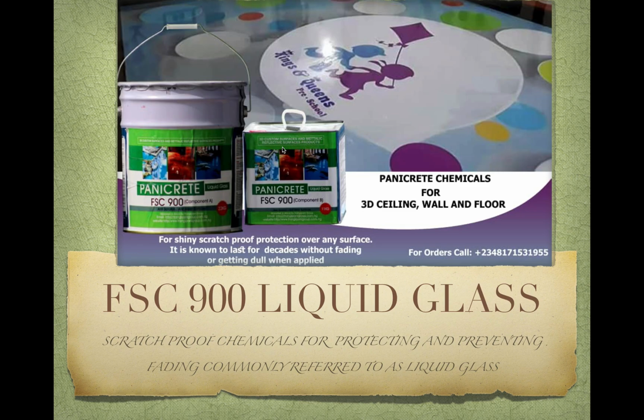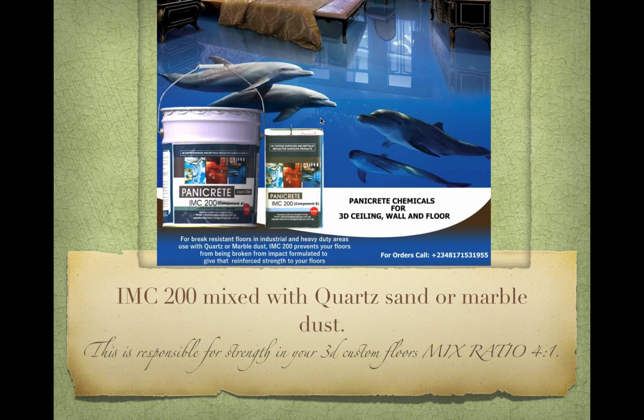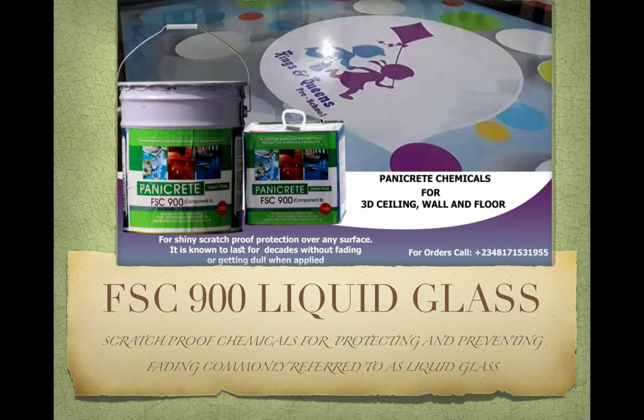Then you have the FSC 900. The FSC 900, also known as liquid glass, you use that to protect the vinyl. After you install the IMC 200, 12 hours later after it has dried, you bring your 3D image and place it over the floor. Immediately after placing your 3D image over the entire floor surface area, you mix your FSC 900.